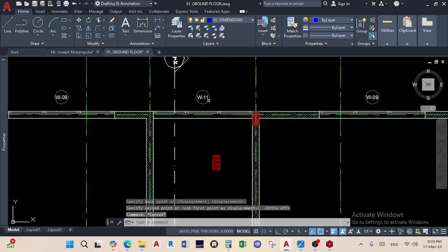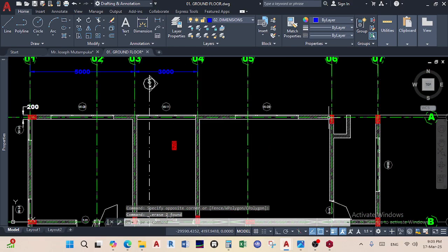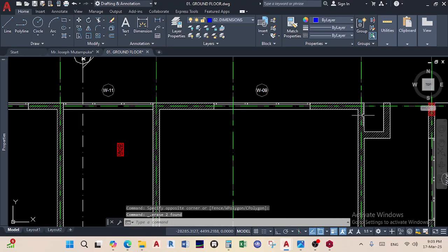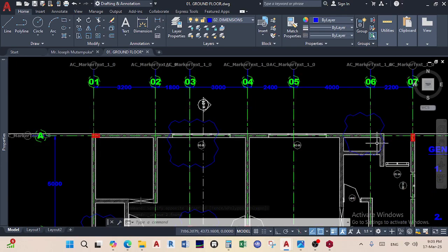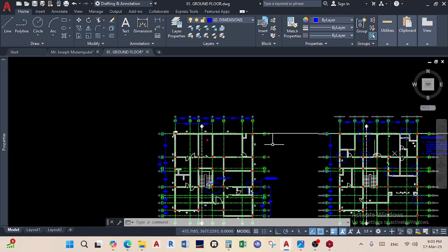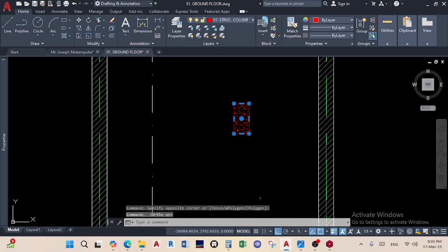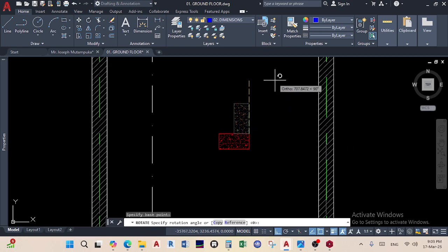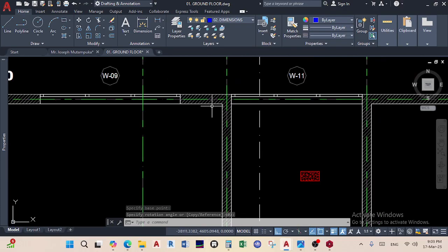And then this one also I need to delete it to change the orientation also. This is the one at 4. At 6 also we need to delete to change the orientation. Okay. So now I'll select this, maintain my ortho, rotate. I'll give it a rotation of 90 like that. And then now I can place it.